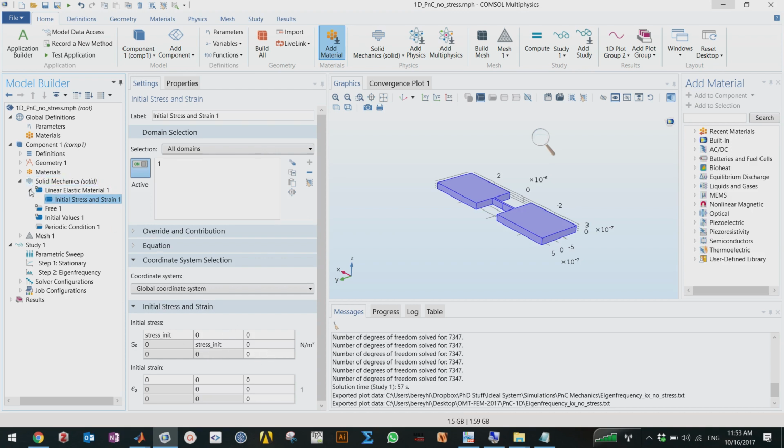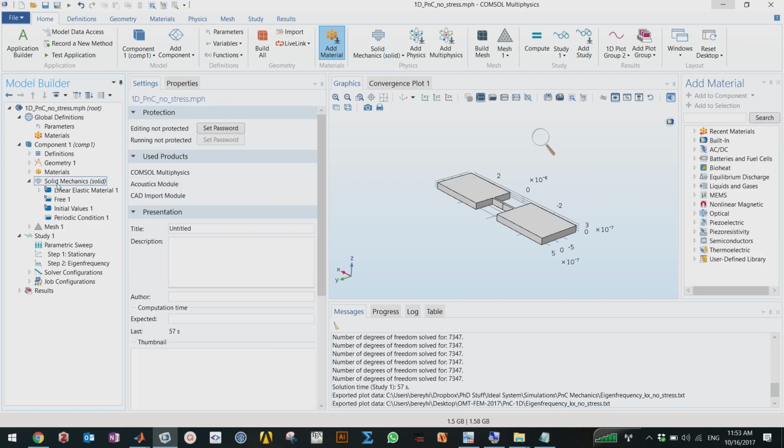Is it also possible to add two parametric sweeps? Yeah. You can add two parametric sweeps, for example, here for different variables, but then it will solve for all the combinations. For example, if this one is n times m, you have a matrix, like a nested for loop.